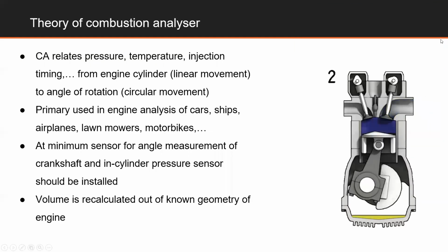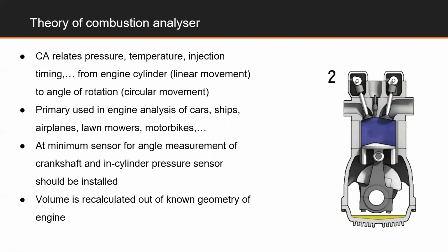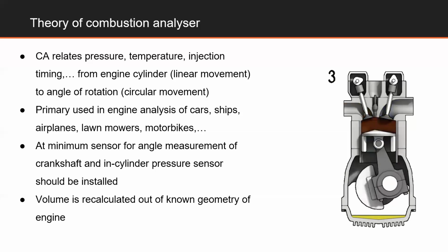To start with, Combustion Analyzer is a bit different than all other modules inside DEWESoft. The main difference is that Combustion Analyzer relates pressure, temperature, injection, all of the analog measured inputs from time domain to angle domain. So in every engine measurement, we are not interested in how everything was changing over time or what the measured values were over time, but instead we want to see how pressure, for example, was changing or what the pressure values were in relation to the current crank angle position.